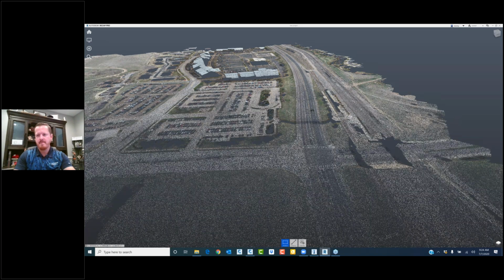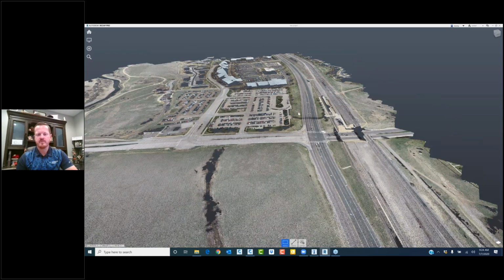And Shawn, a question is coming in from Jared. He says, is the classification being evaluated by InfraWorks, or is it predefined on the points in the point cloud? So if your point cloud is already classified, it's going to further classify it in InfraWorks. If it's not classified at all, it's going to do the initial classification in InfraWorks. So either way, it's still classifying in InfraWorks. It always helps if it's already been classified in whatever product, whatever platform you're using to create that point cloud. But it is processing and classifying further in InfraWorks.